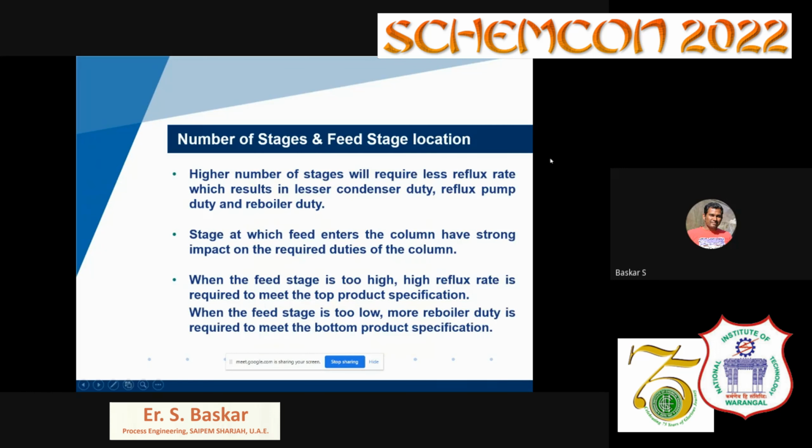And another variable is the number of stages and the feed stage location. This is very important because the number of stages and the feed stage location play a very predominant role in the optimization of the energy consumers. We all know that the number of stages and the reflux rates are interlinked. When there is a larger number of stages, it will require less reflux rate. And less reflux rate means it will reduce the condenser duty and also the reflux pump duty. In a way, it will help in reducing the reboiler duty as well.